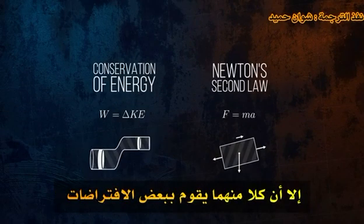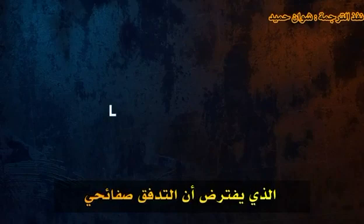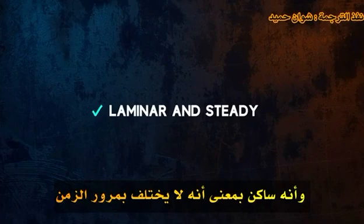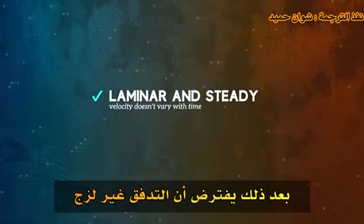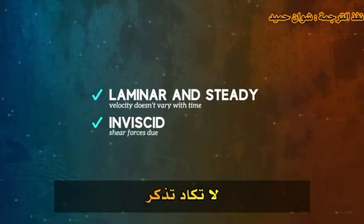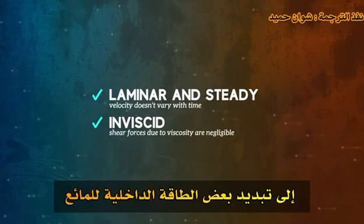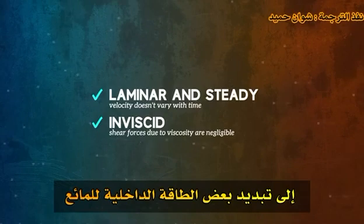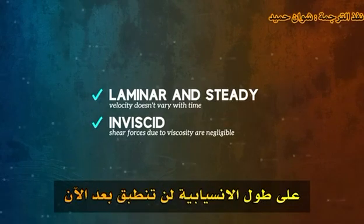they do both make some assumptions that we need to be aware of, since they limit how we can apply the equation. Firstly, the derivation of Bernoulli's equation assumes that flow is laminar and that it is steady, meaning that it doesn't vary with time, like this. Next, it assumes that the flow is inviscid, meaning that shear forces due to fluid viscosity are negligible. This assumption is needed because viscosity would result in a dissipation of some of the fluid's internal energy, and so the idea that energy is conserved along a streamline would no longer apply.